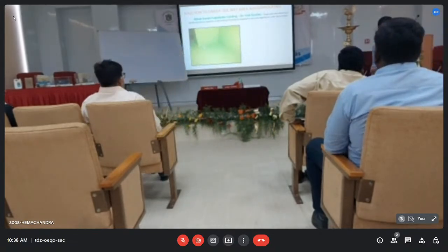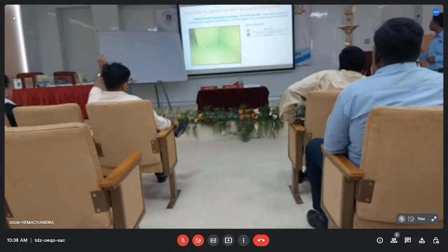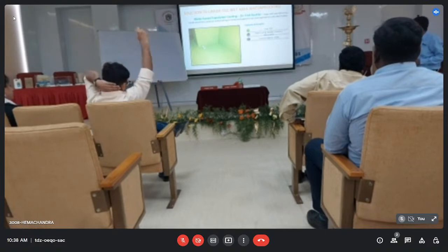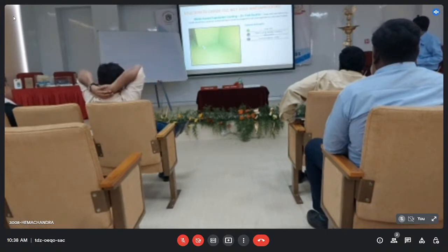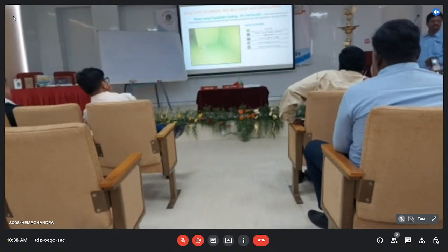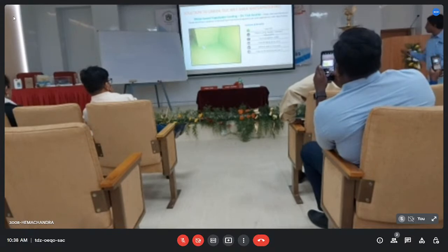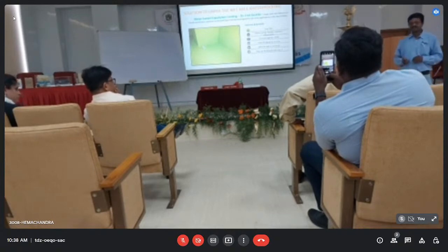So it will look like a single component polymer coating, a co-polymer coating. Features: low VOC, fast curing, flexible, seamless coating, and high elongation. The crack width it bridges will be 2 mm, whereas in other cementitious coatings it will be only 1 mm. Here, 2 mm crack width, and directly you can apply. Directly you can lay your tiles also. No need of a screed.